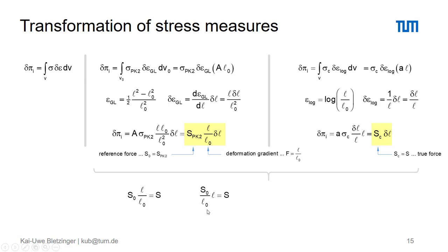And just remember, what is that? Yeah, that's exactly the force density. That's the force density Q, which in the force density method is assumed to be constant throughout the complete deformation, as it is indeed the ratio of two values coming from the reference state, that means the undeformed state.